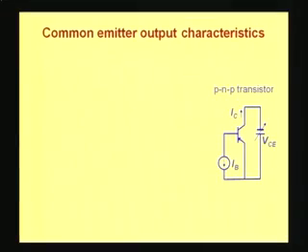So here you have the emitter junction shown by this arrow. The P region is the emitter and the N region is the base. So, P-N junction. The arrow shows the emitter junction. Similarly, you have the collector. This is the collector. This is again made of p-type material. So P, N, P. That is the arrangement. P-type collector, N-type base and P-type emitter.